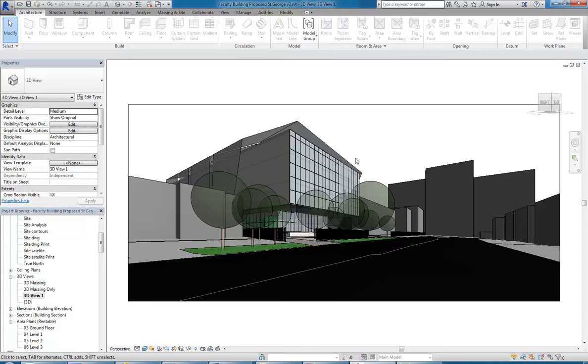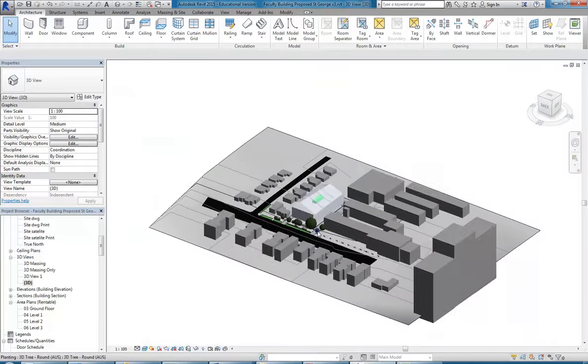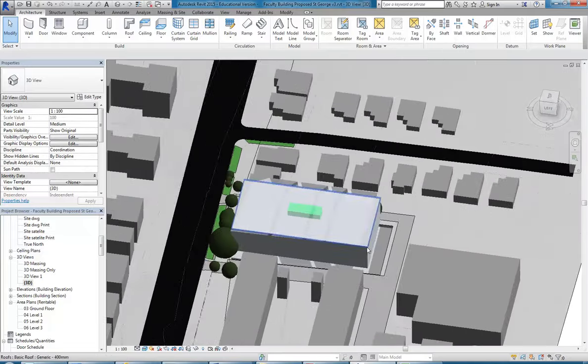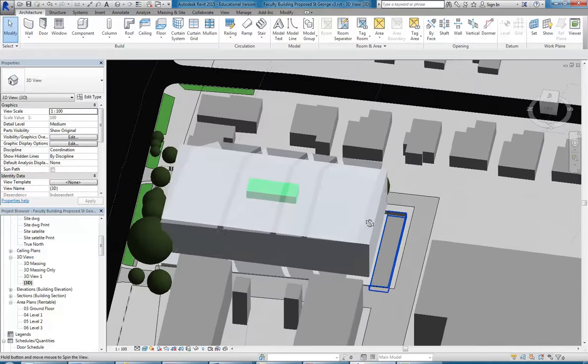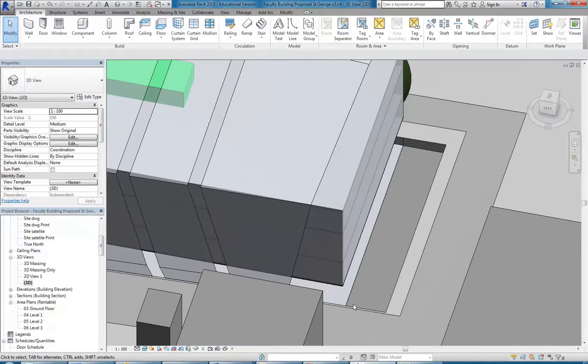Okay, so you can see here I've got a reasonable idea of the shell of my building now, and I want to start modelling some of those elements with a bit more detail. So I'm going to look at using the curtain wall tool mostly, but before I go too far there, I want to also just make sure that my solid walls are going to join properly to these curtain walls. And so what I thought I might show you first is actually just a setup using some solid walls for the, I'm going to do a retaining wall back here.